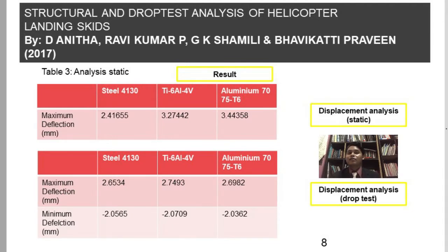we get the result for the maximum deflection for the static analysis and the maximum stress for the drop test. We found that the results for all are almost the same. So we decide that the most suitable material to use is aluminium 7075T6 because it produces the lowest weight.